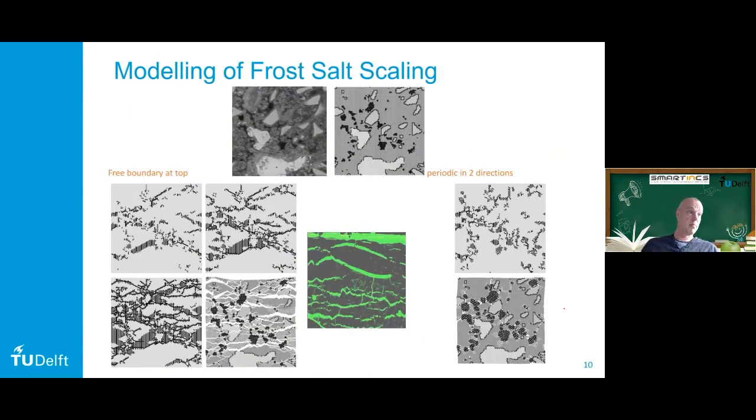We also applied it to different mechanisms, like this is frost salt scaling, where we had water inside the porosity. So here you have the pores, and inside the pores you have water that freezes, becomes ice, and is going to expand and then creates cracks in your system, like you see here, which looks similar to what we observe experimentally. So you can simulate these real mechanisms. And in this case, we don't have an external load, but it's an internal load. So the elements inside the pore, which were water, they freeze and they expand. So you can also have an internal loading in the material.